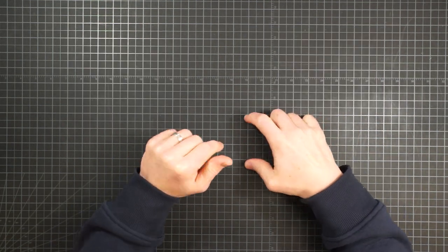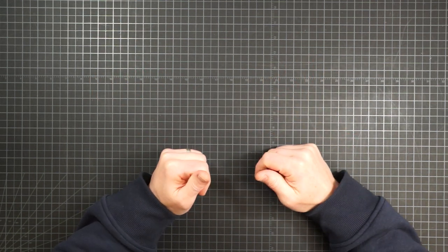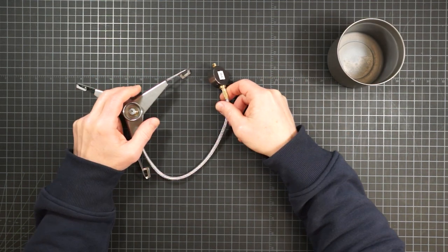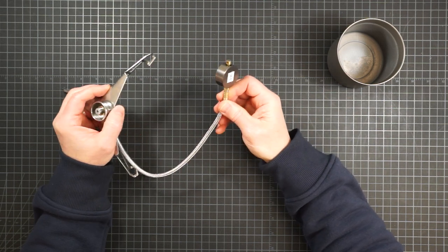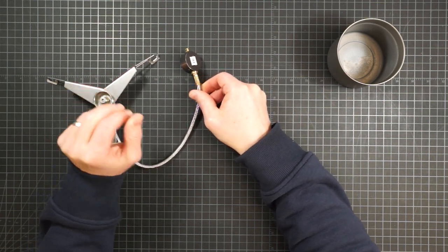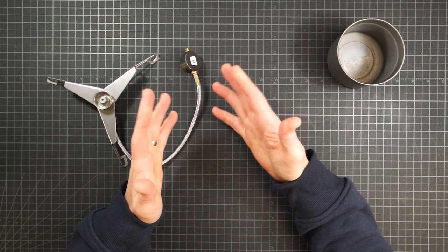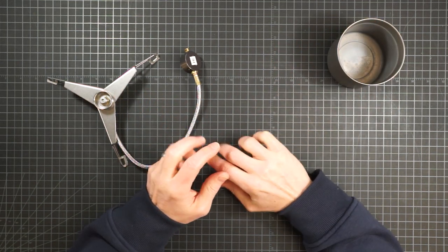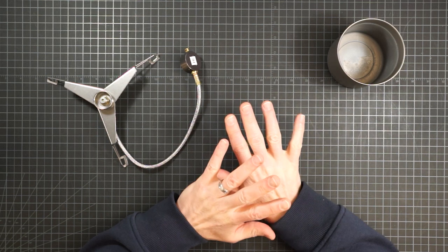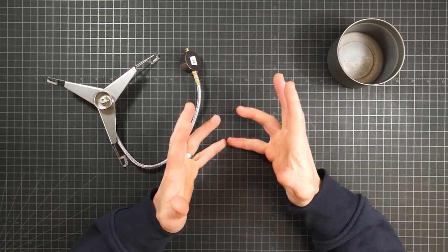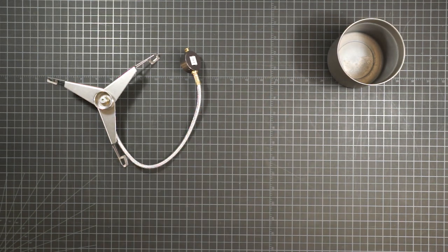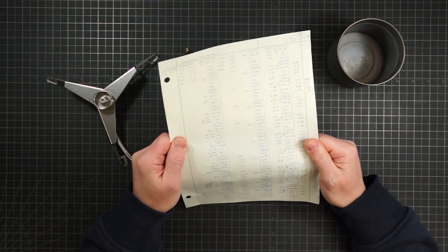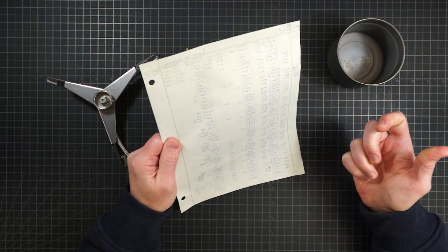I know what you're thinking. Just adjust it back to what it was. Well, easier said than done. These things aren't built for fine adjustments or accuracy and repeatability. Originally, I set high to be just low enough that it wouldn't max out any of my stoves to guarantee that everybody would be passing the same amount of gas. I didn't have to try and match it to anything. In short, I spent days and days doing many tests and simply cannot get it back to what it was before.